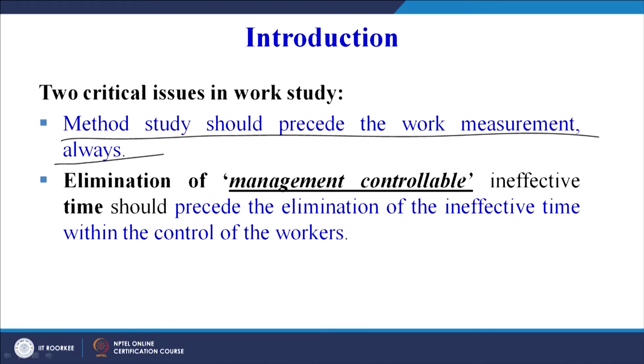Then, elimination of management-controllable ineffective time should precede the elimination of the ineffective time within the control of the worker. As we have seen, in many cases it is because of the management that there is ineffective time for doing that work, the task, or the sequence of operations. So first the focus must be on the management-controllable ineffective time, followed by that we must try to focus on the ineffective time of the worker.